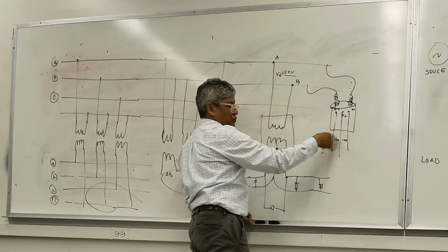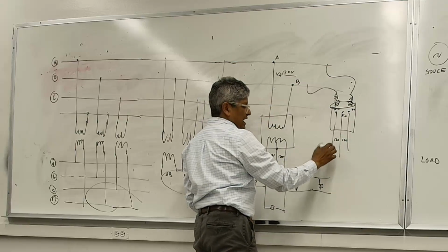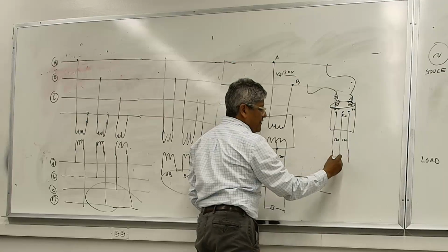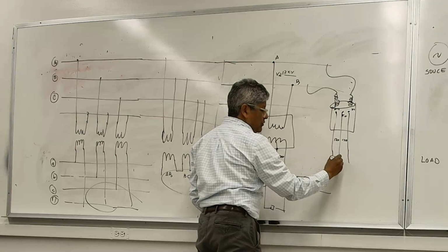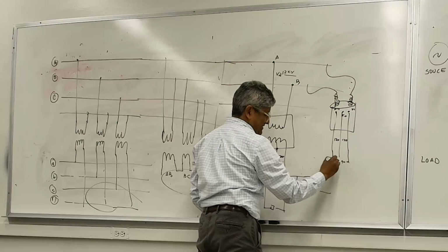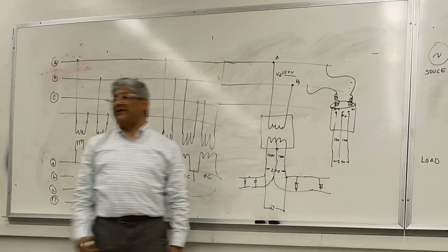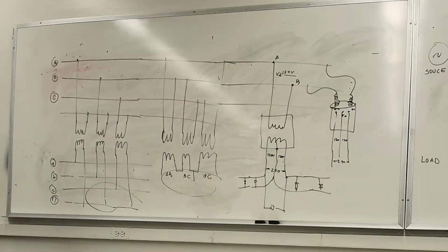So you feed your single phase 120 loads, and then you can feed 240. People call these single phase loads, but they're not necessarily single phase. In reality, these are two phase loads. But we call it single phase 240. Do I make sense, everybody?